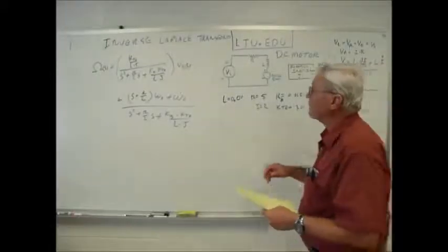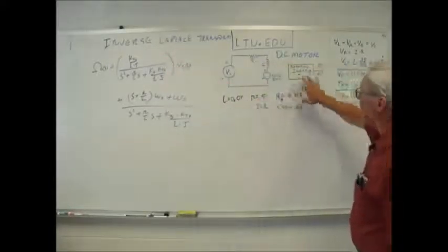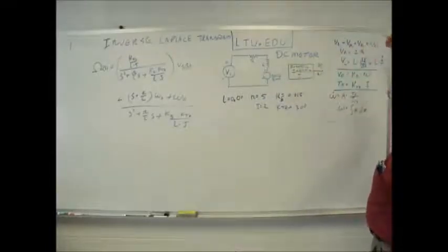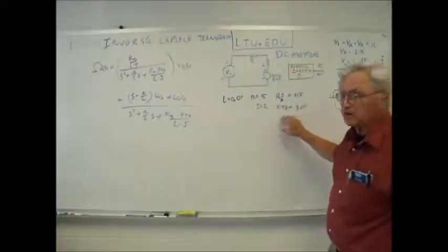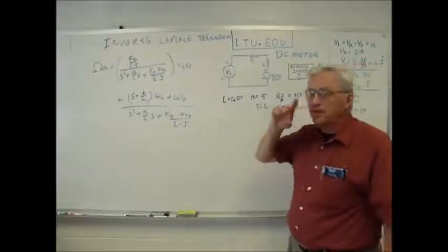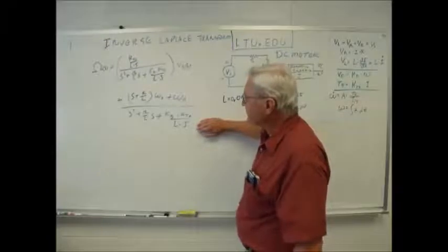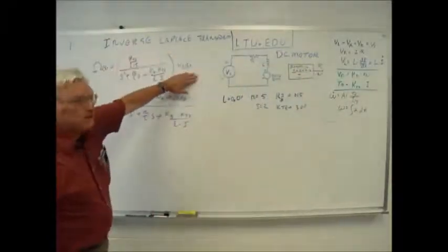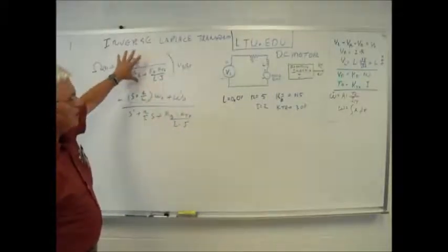Okay, so now we're going to talk about the inverse Laplace transform. We talked about taking an equation for our DC motor. We had the basic Kirchhoff's laws, Newton's laws, things like that. Put that into an ordinary differential equation that we transformed into Laplace domain. Here's our Laplace domain transfer functions. Our output omega of s is a function of the input V of s and is a function of the initial conditions, all in Laplace domain.